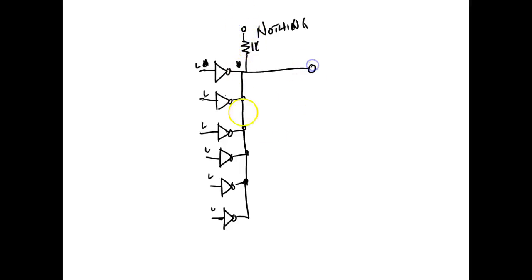And then there we go. Now when all these go low, none of them is going to pull this down, and now the resistor would cause this to go high. Right? You understand? But if one of these went high, it doesn't make any difference. If one of them went high, then the output would go low. This would be ground. This would be a 1K. If this is plus 5 volts, then it's having to sink 5 milliamps.